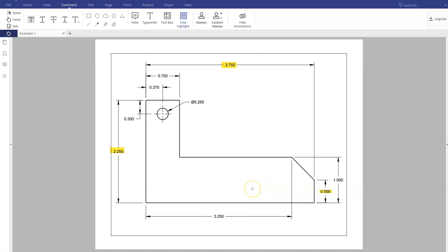But now that we have a better command of doing this, we don't need to go around and figure out how much to go here and this way. So what we're going to do when we come to addressing this corner is continue all the way up with this height of 1, and then we'll go back in this direction and complete this shape. We'll use the chamfer command, and I'll show you the way that we're going to do that in order to create this chamfer on the end.